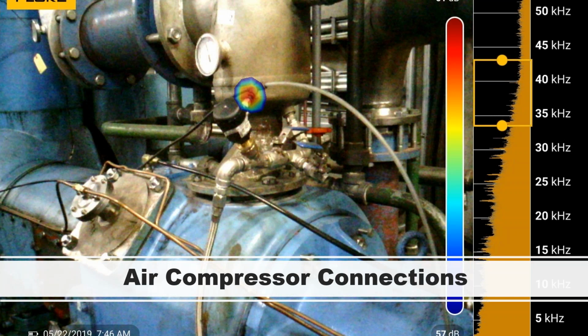It's probably pretty loud there right next to the compressor, wouldn't you say, Michael? It's very, very loud, yeah. Is that what we're picking up? And if you look at all that stuff below 25 kilohertz, going up and down is your frequency, and going left and right is your decibel level or your loudness. There's a lot of machine noise going on right there. But you're able to pick up that minute air leak on that small tube with all that equipment running.